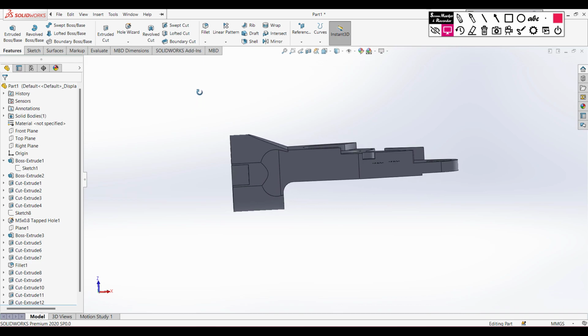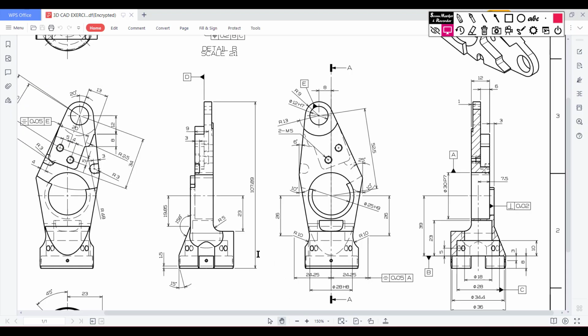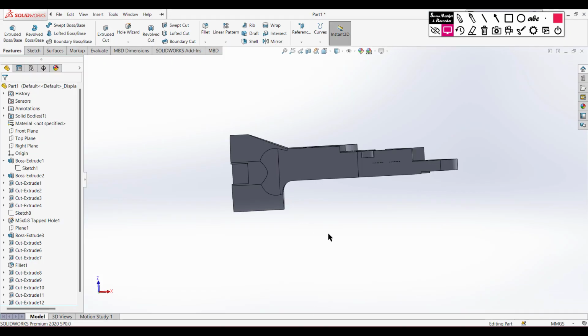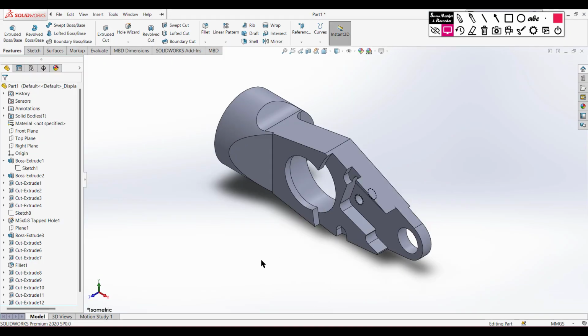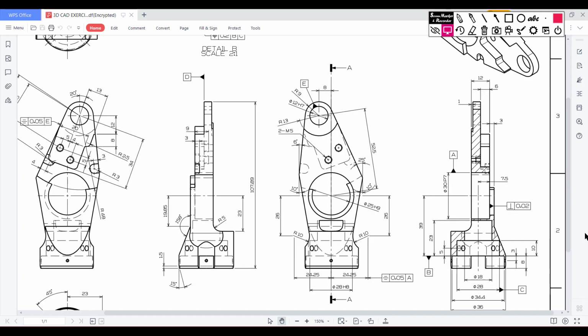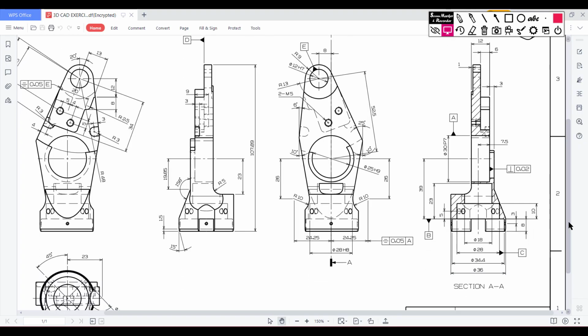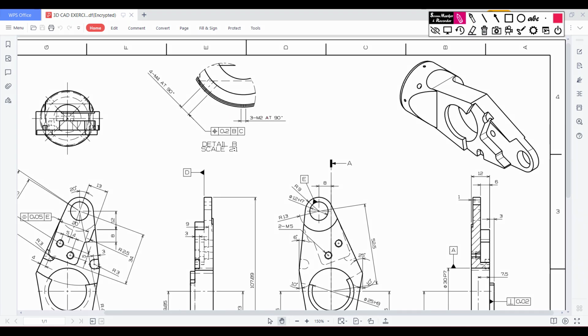Okay, so if we look at this one, it is quite matching our shape. Okay, so now isometric it for a better view. Now move to next portion. So in our sketch we can see we have some M2 extrude cut and M4 extrude cut, and for our ease of drawing we will use a 2 diameter circle and a 4 diameter circle. I am not using M4. If you have time you can use the hole wizard with M4 unit and M2 unit.